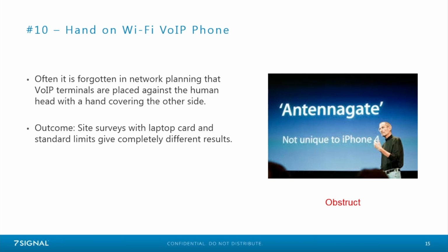This one specifically is talking about VoIP phones that you're holding up against your head, covering with your hand, and that's going to soak up a lot of energy, and it's going to give a lot different reception characteristics than if you did a site survey with a laptop, perhaps even with an external card or a USB adapter hanging out in free space.